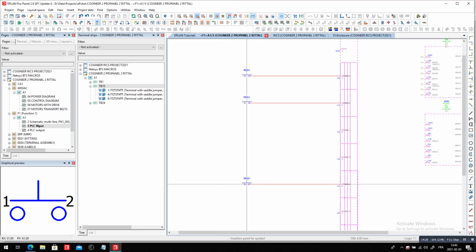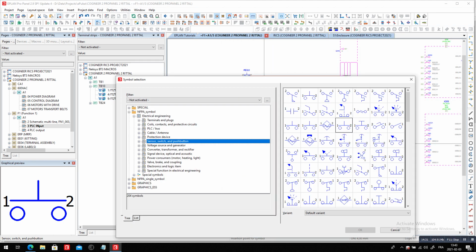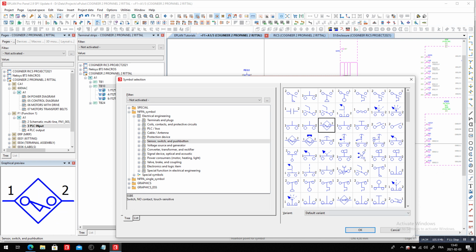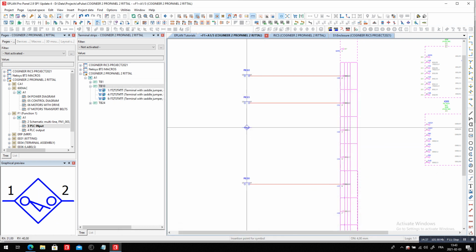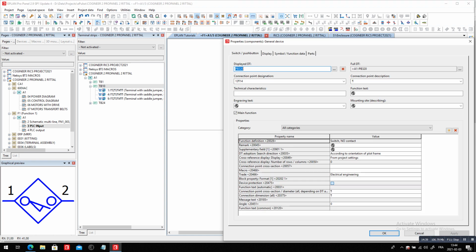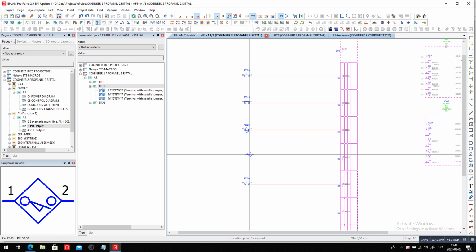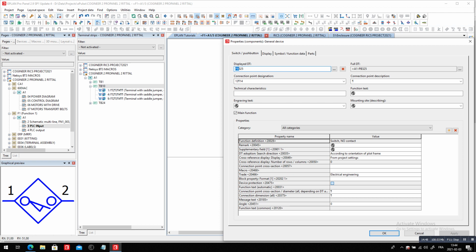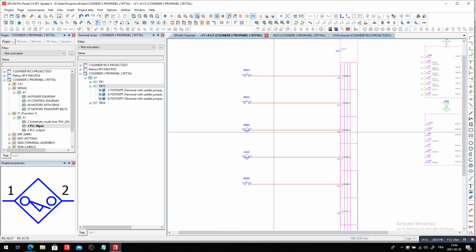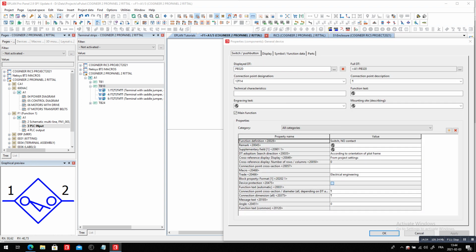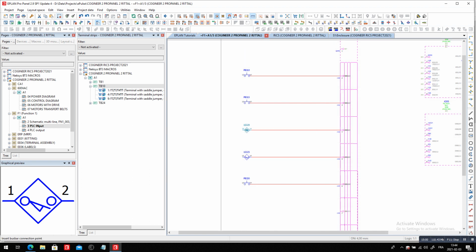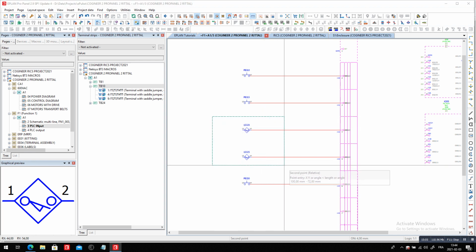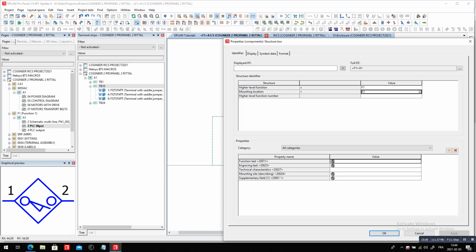Then you have other signals that actually are out in the field. So technically what happens is that you may have 2 limit switches or proximity switch, any kind of signal, but these signals that are here, I'm just going to change very quickly their designation because I don't like them to be LS, PB, I prefer them LS. So this one is LS. And what I'm going to do also is I will specifically say that this is out in the field. So I'm going to use here the mounting location to just redirect them. And this is outside of the panel. So here, mounting location F, and we know this is out in the field.